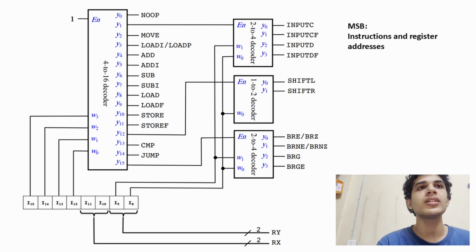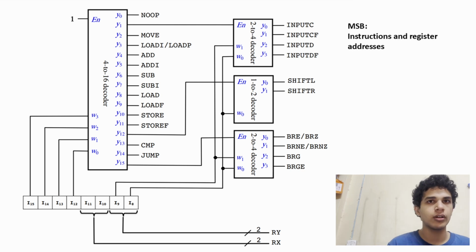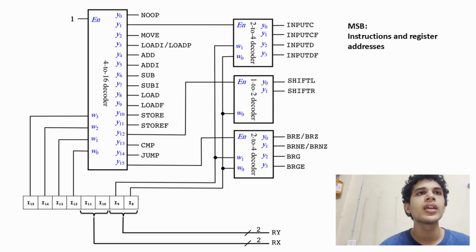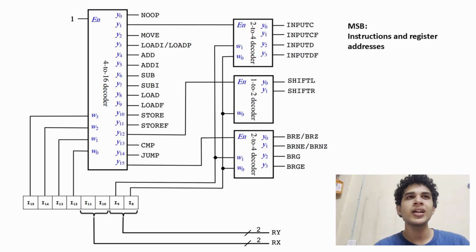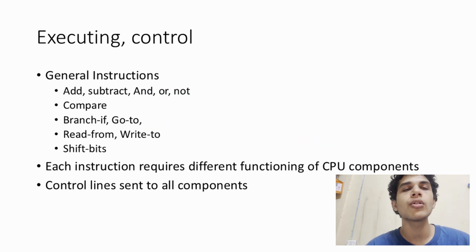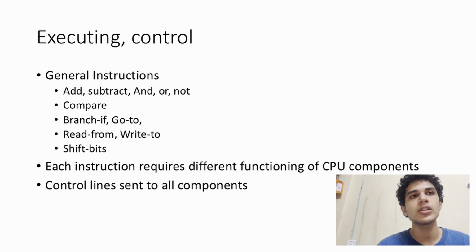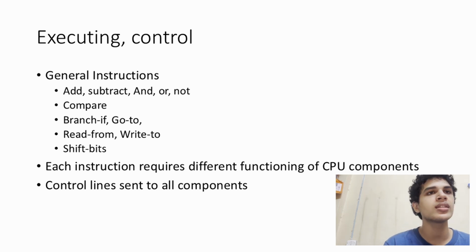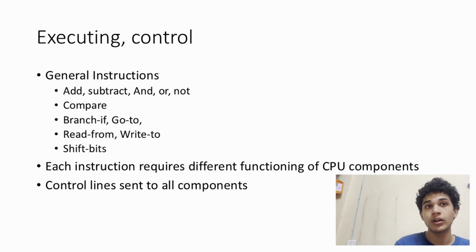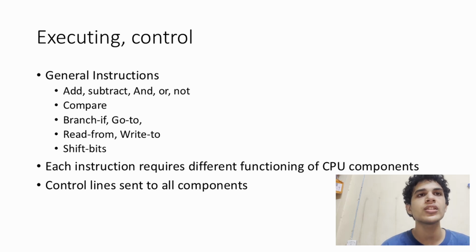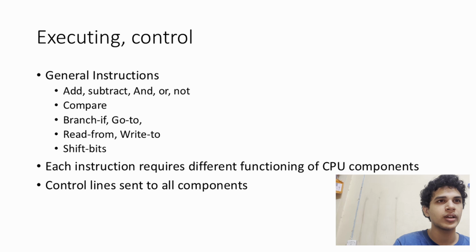Now, instructions themselves are encoded and stored for the convenience of reducing the number of bits required to store them, and of having a certain format. What that means is that in order to make the control logic more convenient, they require decoding. In the case of the 281 CPU, the opcode detector takes the 8 high bits from the code memory, which refer to the instruction, and it sends 27 one-hot lines to control. The 27 one-hot lines each correspond to which instruction to carry out, and only one out of 27 is on, corresponding to which instruction is to be carried out next.